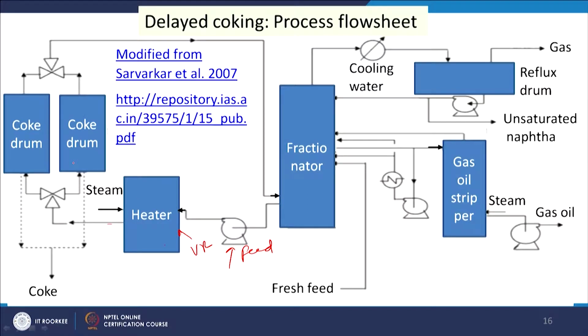So, high temperature here and pressure is applied and then for a longer period the coke stays here, that is why it is called coke drum. So, after heating the VR and steam, it is going to the coke drum, it remains here under high pressure at high temperature, then vapors are going out, then they go for fractionation.